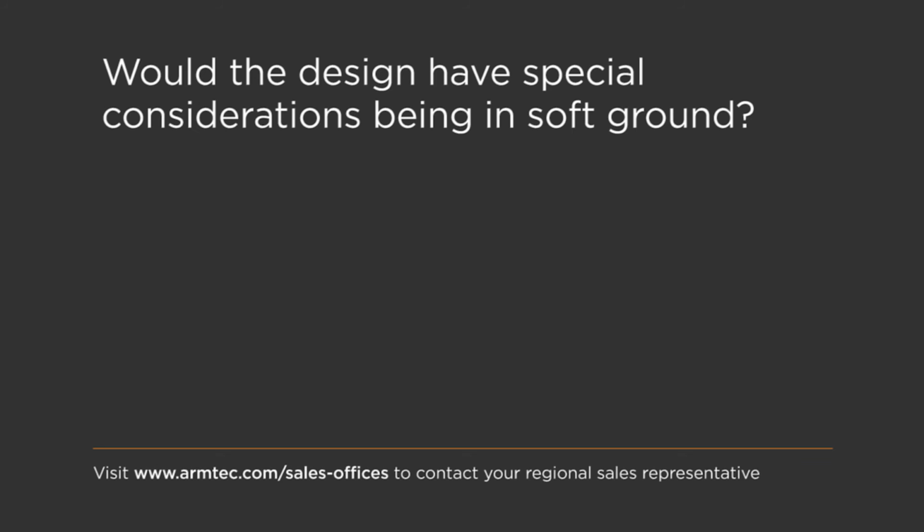However, again, generally speaking, if the foundation soils are soft or mucky, the best thing to do is to excavate below the grade line and backfill to grade with suitable material that will adequately support the weight of the pipe and the backfill. If that's prohibitive, there are other ways to tackle that by reinforcing perhaps the foundation soils, but that's usually done by a more geotechnical specialized consultant.